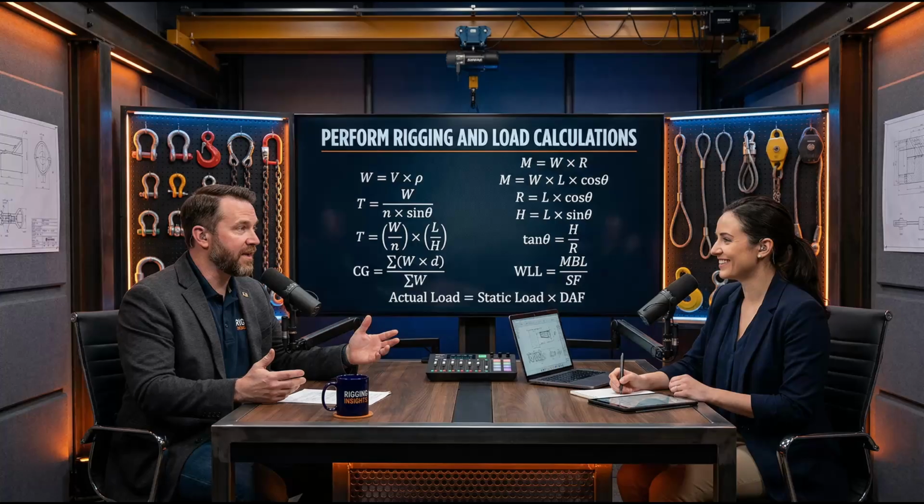20 kilometers per hour is roughly 12 miles per hour. It is barely a brisk breeze. It might rustle the leaves on a tree or mess up your hair slightly. Yeah, but when that breeze is pushing against the massive sail area of a suspended cargo container, the squared velocity generates enough lateral force to cause a catastrophe. Because gravity, geometry, and dynamic forces are so severe and the consequences of failure are so catastrophic, the equipment we use cannot be operated anywhere near its true physical breaking point.